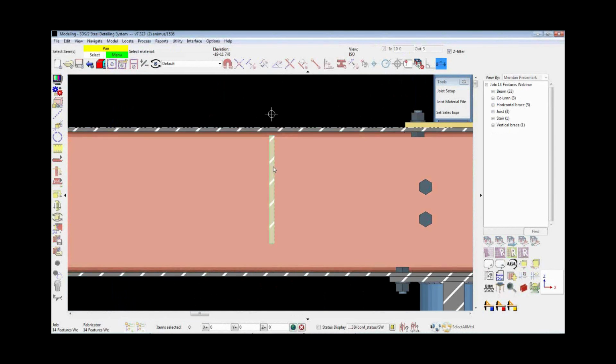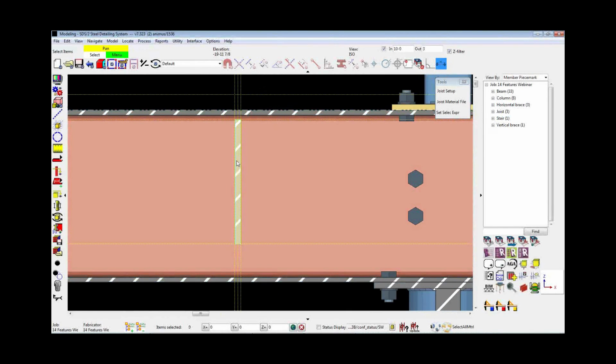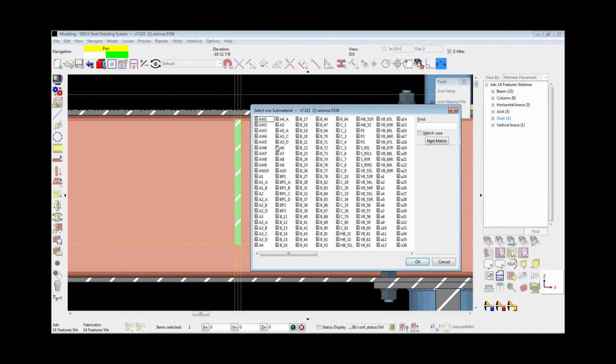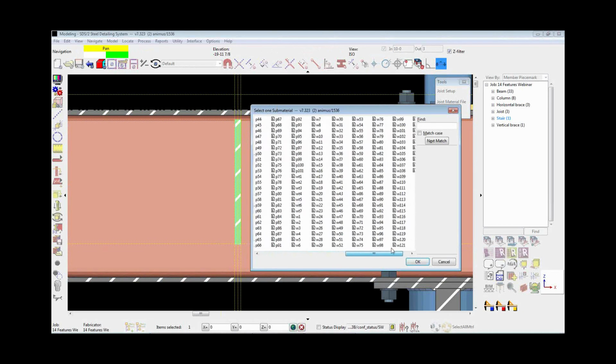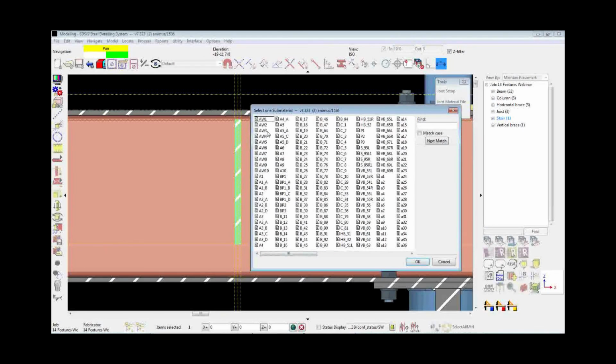So just real quick, I'm going to come over here. I'm going to use material add, construction line add material to get construction lines in there quick, and then I'll pick my material add existing, pick the member I want it added to, locate my points, and now I have all my materials that exist currently in this model to add.